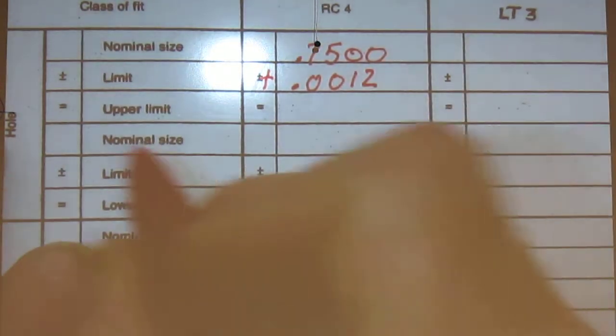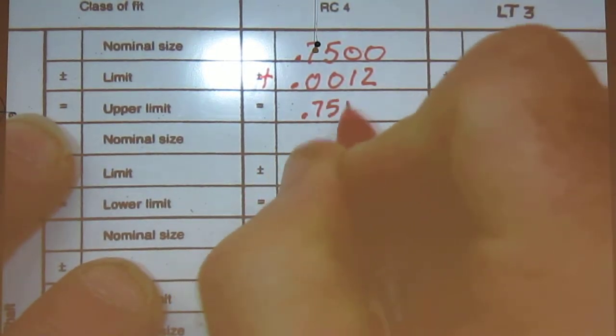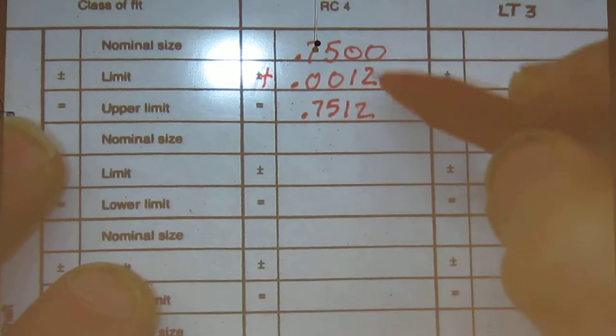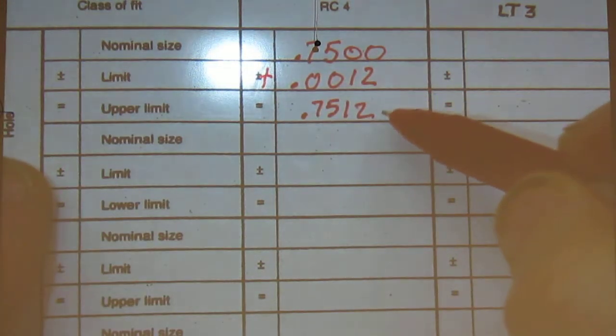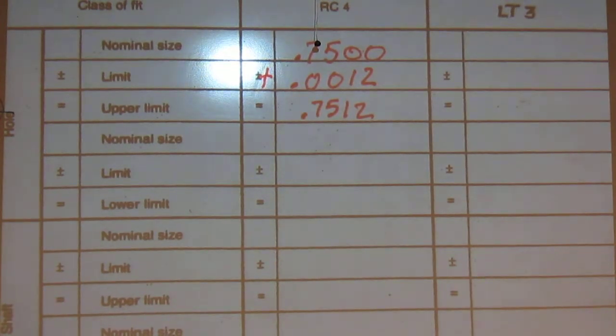Then we just do the math, and it's saying what's the upper limit of the hole? So this is 0.7512. Wait, where'd you get that one? I added the two above it. You add them together. That's why it's got a little equal sign on there. Oh yeah. So when these holes are machined, the biggest hole I can get is 0.7512. Now, keep in mind, if I've got a big hole, is that maximum material condition or least material condition for the hole? Max. Because you said the biggest. When a hole is biggest, it has the least amount of mass. So this is the least material condition for the hole.